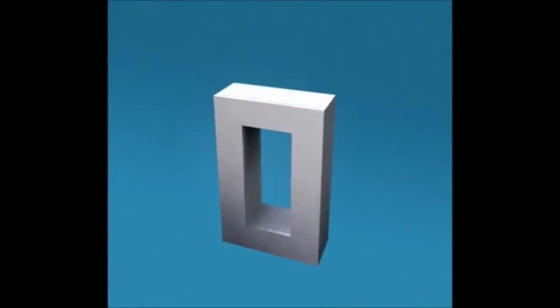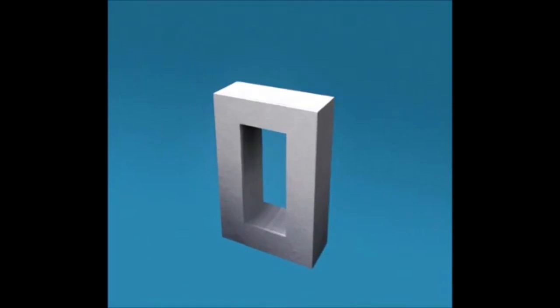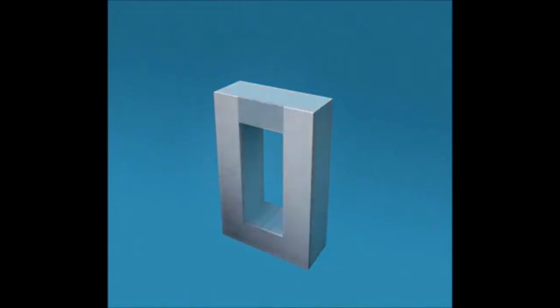Laminations are made up of a highly permeable material, that is, silicon steel. These laminations are assembled together to build a solid core. The resistivity of the steel sheet itself is high, reducing the eddy current losses while making the laminations very thin.